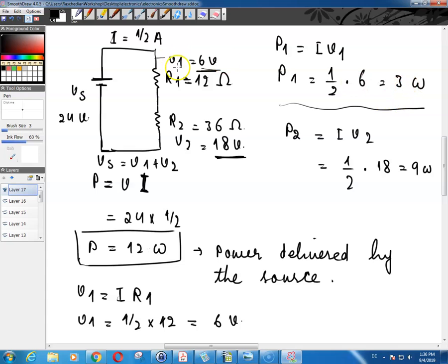For example, if you place a half watt resistor over here, it will burn in probably 10 seconds or so. Or over here you need at least a 10 watt resistor or so. I don't really know if there is, for example, a 12 watt resistor. I don't think that you would find that, but 10 watt is something that you can find. So that's basically that.